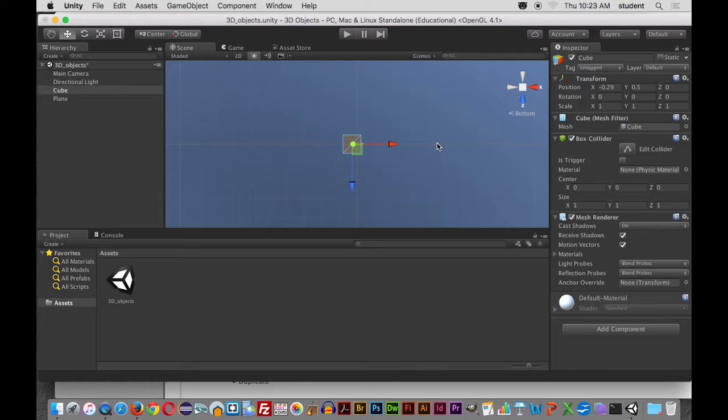If you flip it, you'll notice that it seems to disappear, but it's actually still there. Because it doesn't create a face, it's not what they call double-sided. It's only single-sided. You're only going to see it from the top view. If you angle it even slightly, you can still see it. But if you angle it so that you're seeing the bottom, you may lose the view of the plane.